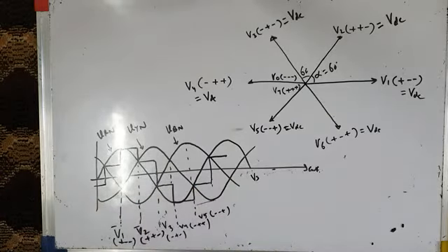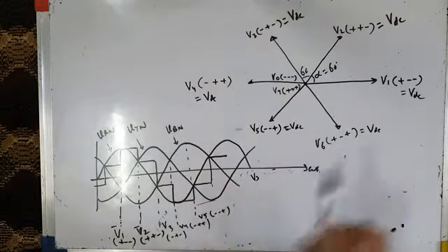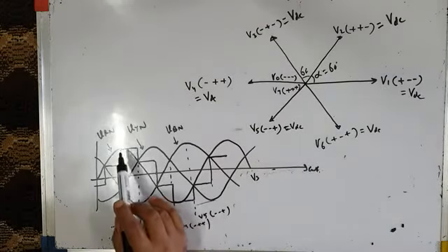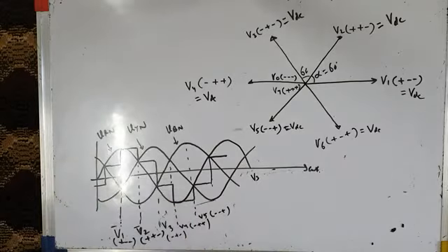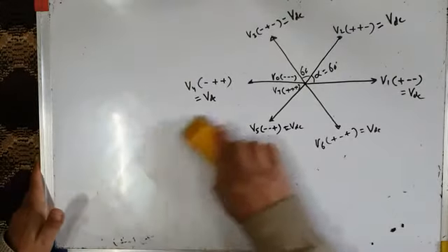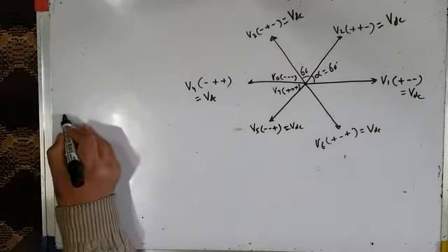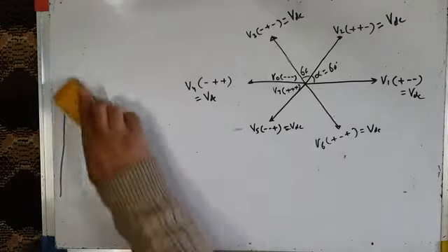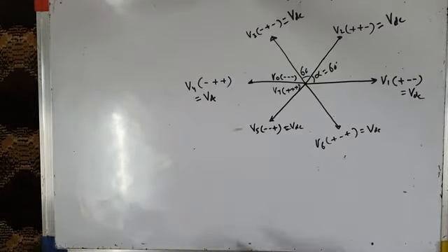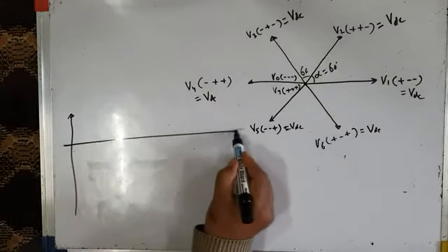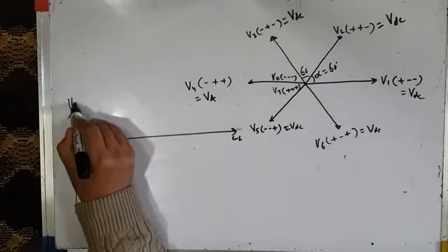and you can see it is a 6-step voltage. So therefore, when inverter is operated, initially voltage vector V1 equal to VDC gets applied across the load, which represents phase R voltage equal to VRN. Let me draw all these three phase voltages for better clarity. This is just a recap of what we have already learned in the previous class. Let me draw VRN.